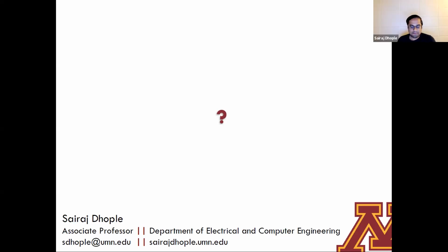I think that's a very broad system level question. There are lots of limits that do come about. It depends on the type of loads that you might have. This idea of inertia, I just want to say that you have to take this with a little bit of caution, right? Because it comes from the synchronous generator world. And if you think about an all-inverter system, even that idea of inertia doesn't really hold that much water, right?